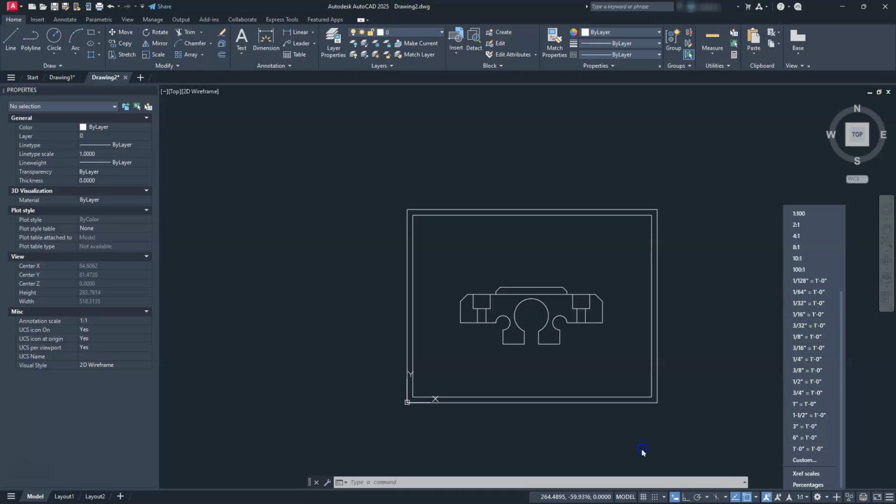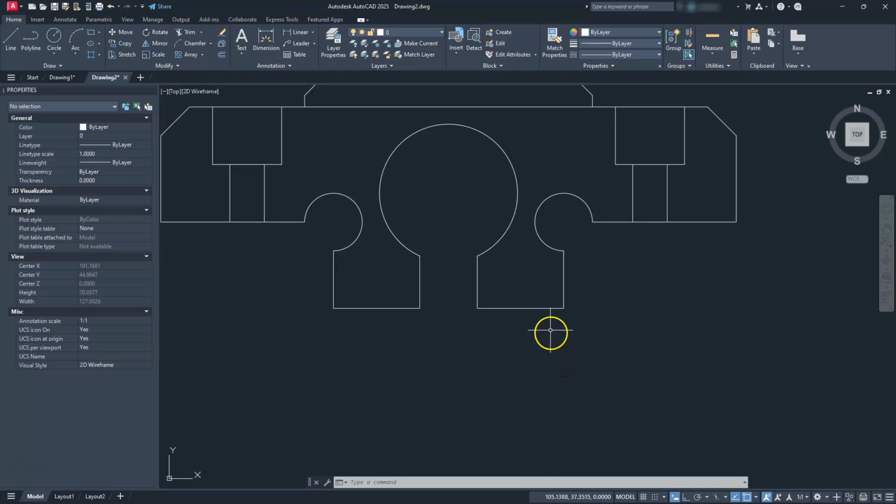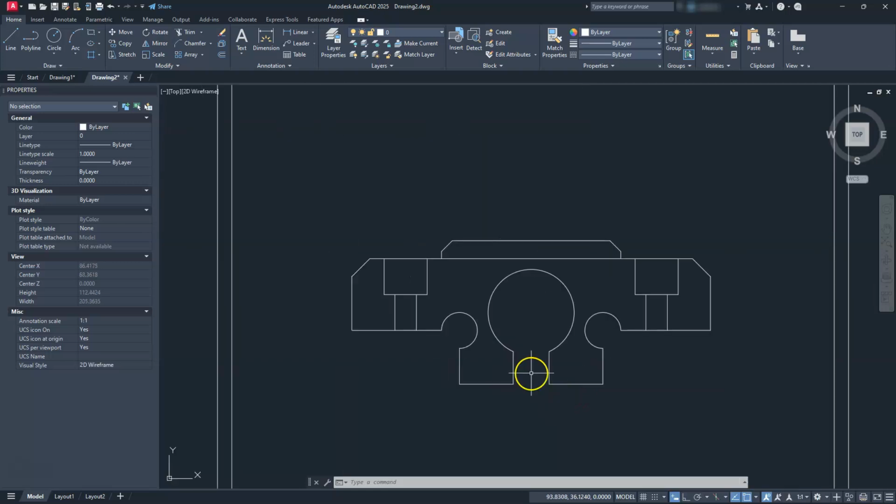But anyway, I'm going to use the standard method of doing this, which means I'm going to input everything manually. All right, so the first thing I do is, since I have my scale factor, I'm just going to type in LTS, hit enter, and then type in 16. All I did was adjust my center lines and center marks and hidden lines and all that stuff so the line types will show up. I'm going to zoom into here.